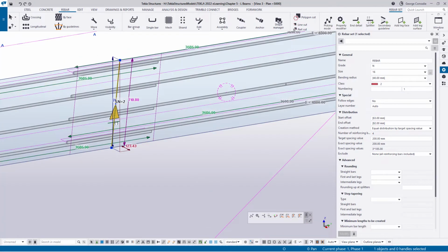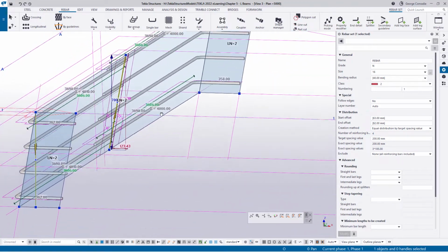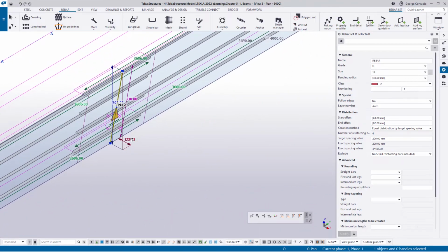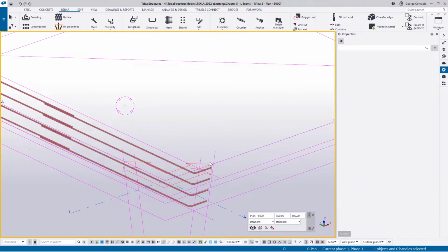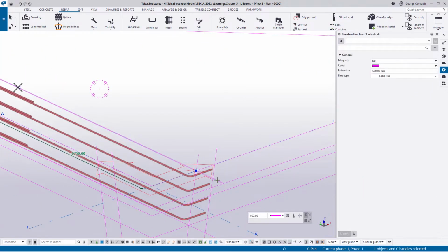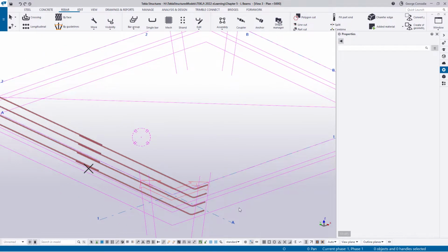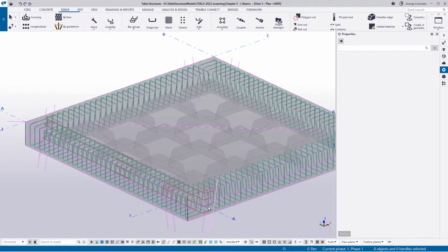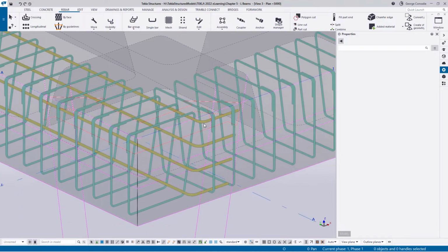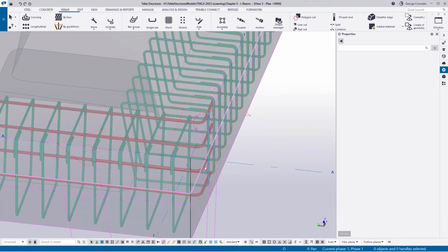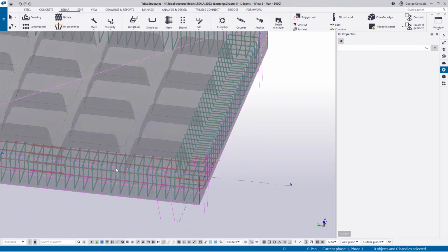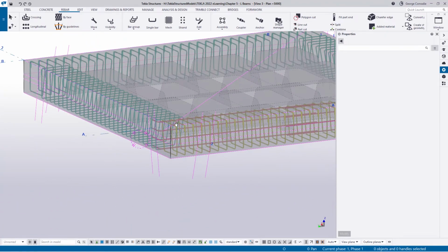And you can see it's now got that tapered edge there, no problem. So that's the way to get around that. And now we really don't need that line and that line anymore, so I'll just remove them as we deal with them. And if I do a redraw, you can see that these tapered bars came in very nicely. It's even respected the fact that there's a bar there. It's got the edge right there, and on the other side, it's the same.